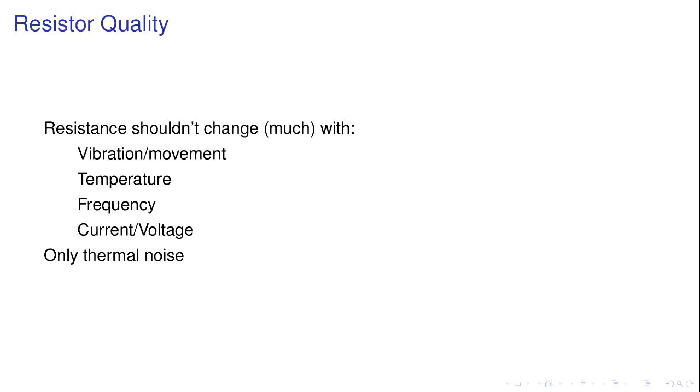Anytime you've got an impedance in your circuit, you're going to have noise proportional to the square root of the temperature times the resistance times the bandwidth over which you're measuring. That's why, if you've got a radio telescope, you put your preamp right there, you run it at a low impedance, typically 50 ohms or even less, and you cool it with liquid nitrogen to keep it low noise, and you use a very restricted bandwidth that you're looking at.